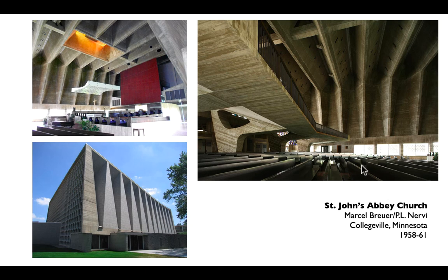And Breuer, being a good brutalist, is going to show you every bit of the concrete formwork that went into making this. Notice too that this again is a portal frame, right? Pins down here at the ends on this giant transfer beam, and then great depth up at the corners where the bending moment is going to be the greatest. And what's happening here really is that the girders, the folded plate girders that span the space, merge into what are essentially folded plate columns that support them.